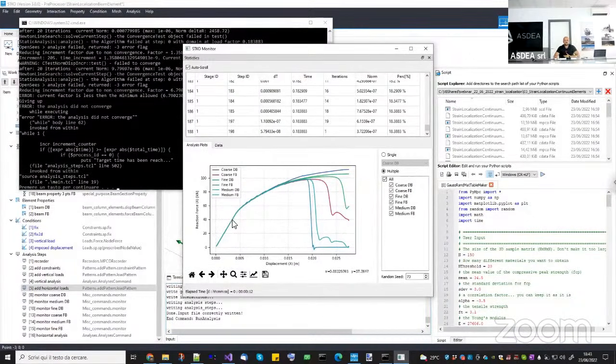Now, as you can see, you're using the same material model, but for 3 different meshes with 2 different finite element types. So you have 6 different columns, and each one of them is showing a different output after the peak point. Okay, so the solution is stable with strain hardening, and up to here the concept of finite elements works. But after the peak point, the concept of refining the mesh does not hold anymore, and you obtain 6 different responses. Some of them are so brittle, like this one, that convergence is not even possible, even with a very small time step.